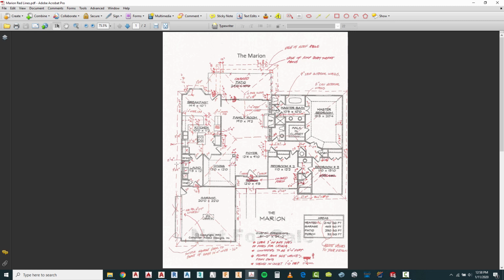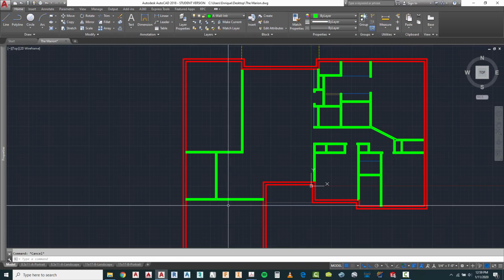We also have a couple of broom closets in here. In some cases, I would probably tell you, let's do one bigger broom closet and leave this one out. So we'll modify this one a little bit more also. If you notice, we give you the dimensions for the depth of the broom closets if you decide to do 1 or 2. So let's just start with one that's going to be about 2 feet wide and 2 feet 4 inches deep.